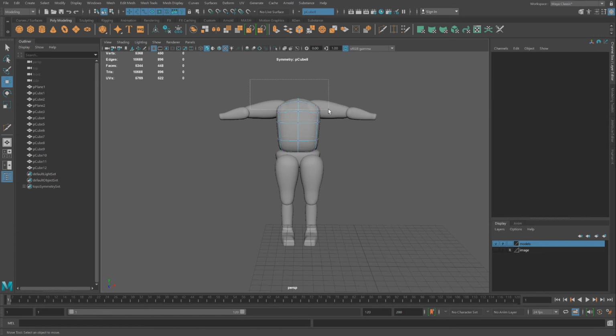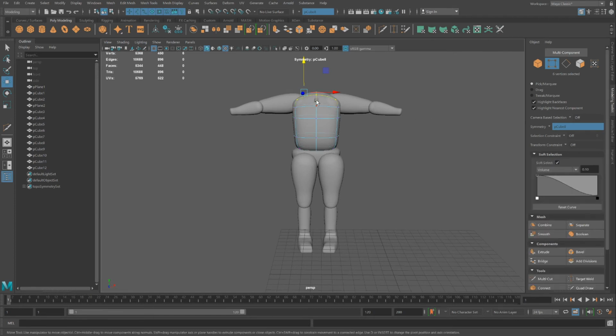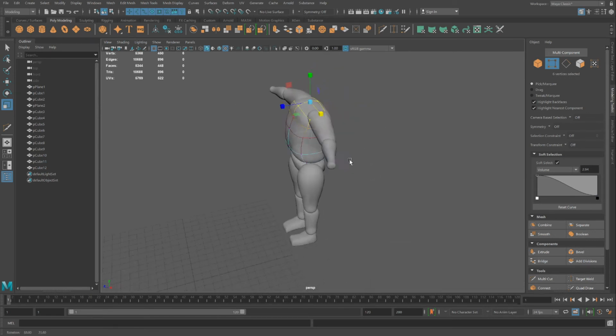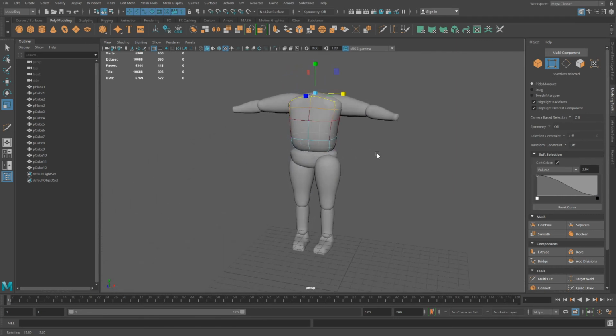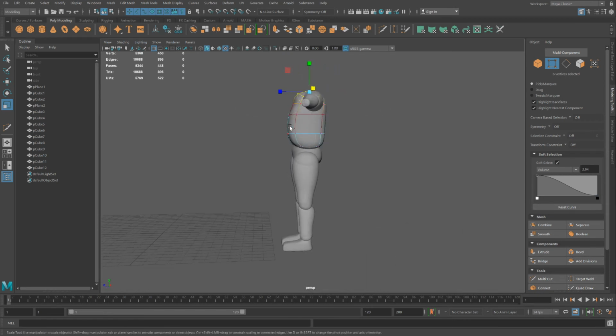by using a soft selection actually up here. Going to modeling toolkit, turning on soft selection, holding down the B key, and increasing and decreasing soft selection. Let me turn off symmetry, and I'll scale it along one axis. Non-heroic, heroic. You decide how round or boxy your character should be. And it doesn't have to be all one shape. Here, as it goes from heroic with broad shoulders, has a bit of a tummy.